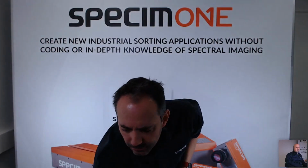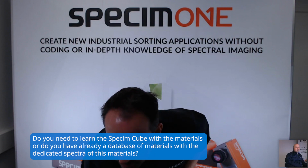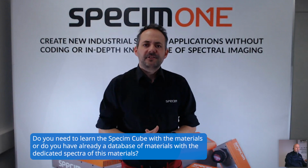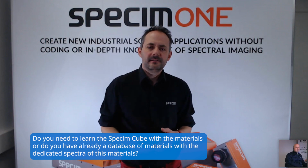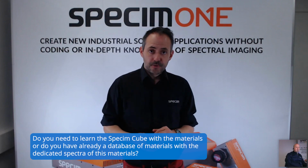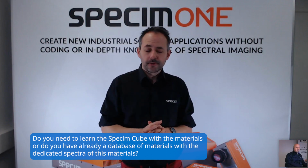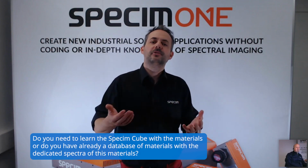Do you need to train the Specim cube with the material, or do you already have a database of materials with dedicated spectra? No, at Specim we do not provide a spectral library. Of course, we have made some feasibility studies and we know some of the materials. For example, on our website there is a blog where you can see the spectral signatures of different types of fabrics and different types of plastics, but we do not provide those. So basically, you need to create your own spectral library with the samples you acquire.